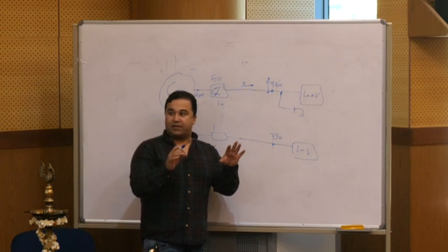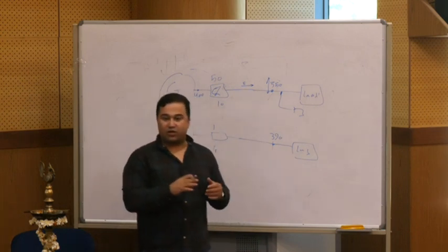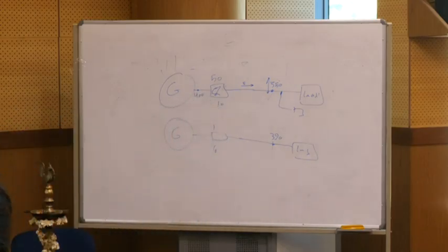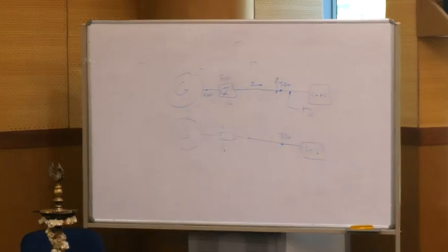Did you get it? With this type of network, a fast system is not needed because the grid damps the fluctuation. But in the future grid, we know that we will have more power-electronic-based generators and fewer synchronous generators. So we can predict that the future grid will not be as strong as we have now with synchronous generators, so it will be more dynamic.